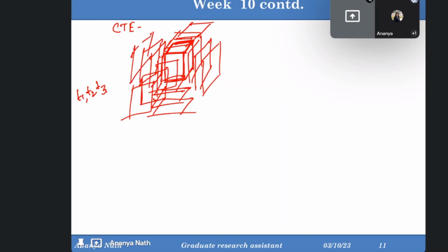Ma'am, I think these are planes parallel to the different faces of the cube, right? Yes, the drawing was somewhat like parallel planes around the equiaxed particle, and those parallel planes are called punched dislocations.